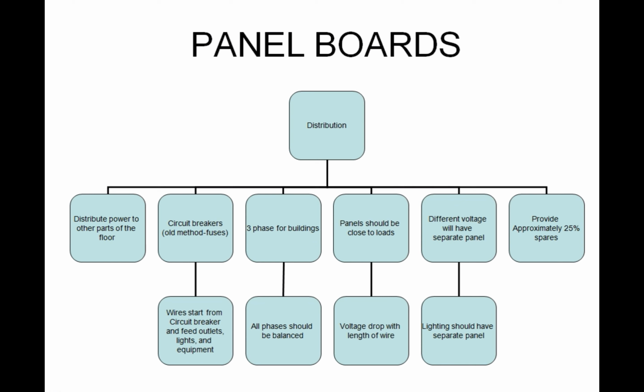There's a number of them connected to each of the breakers, and the breakers, as we saw, are rated for a certain amperage, and then you can only install as many outlets or receptacles or lights as those breakers can handle, or they'll continue to trip.